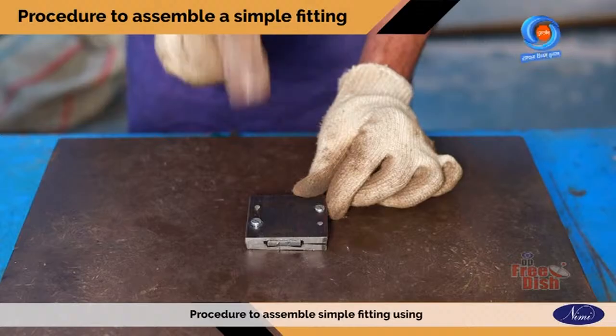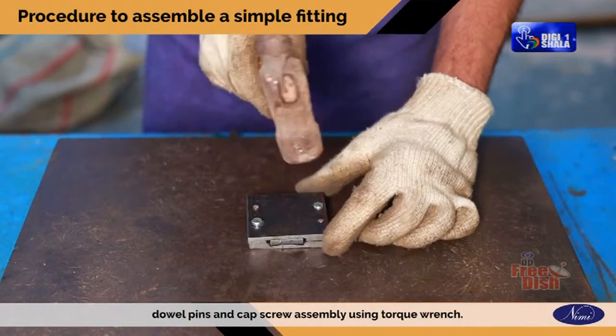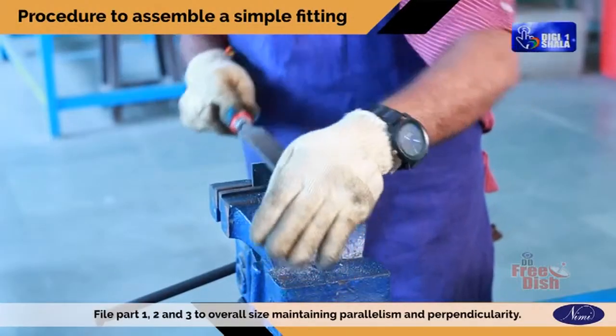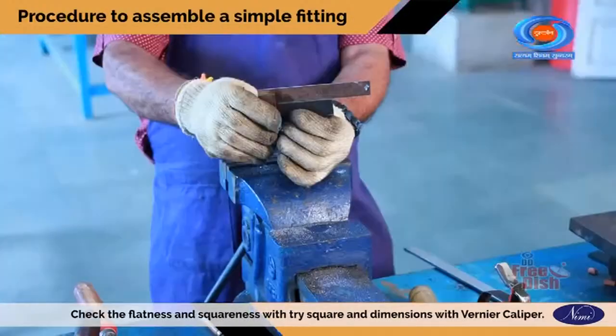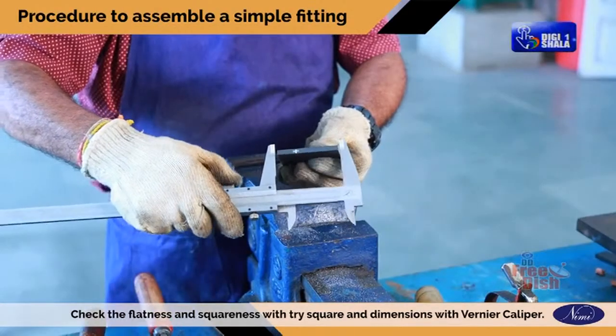Procedure to assemble fitting using dowel pins and cap screw assembly using torque wrench. Check the raw materials size. File part 1, 2 and 3 to overall size maintaining parallelism and perpendicularity. Check the flatness and squareness with tri-square and dimensions with vernier caliper.